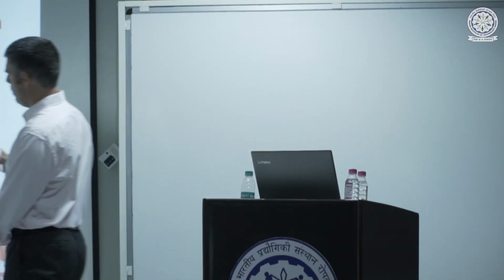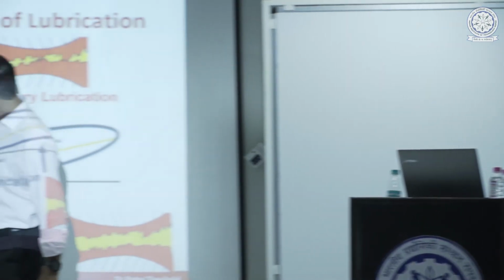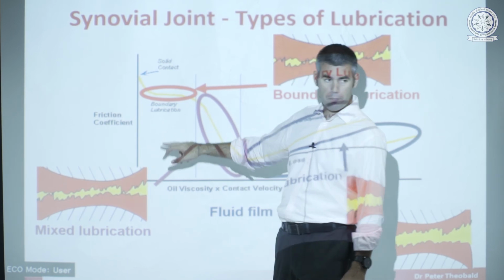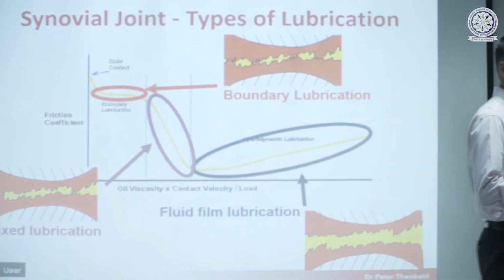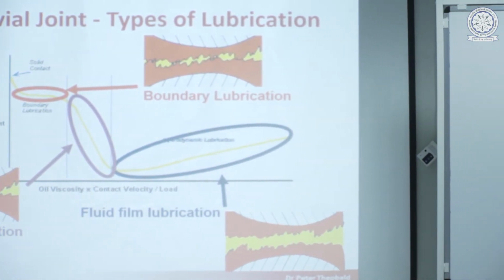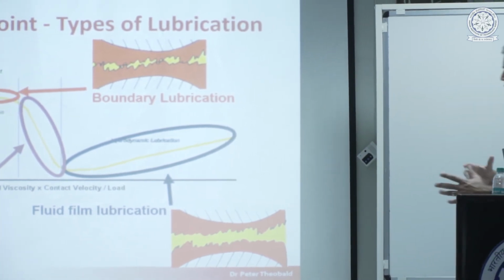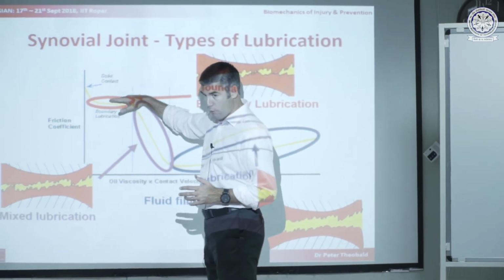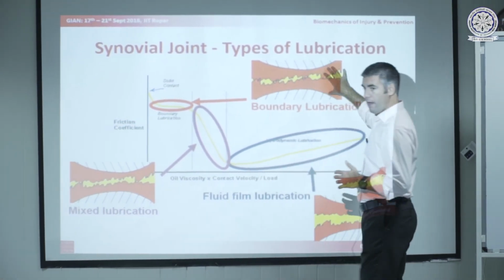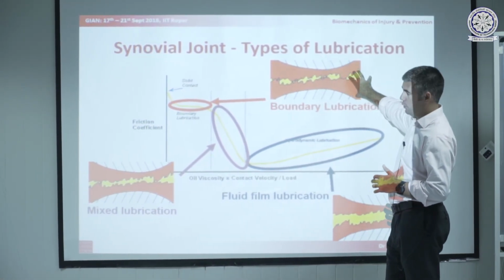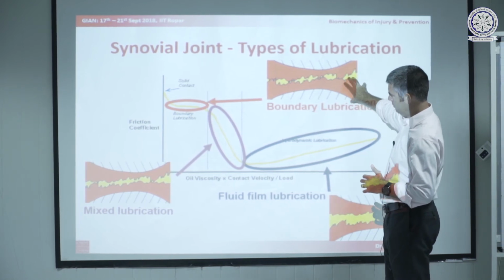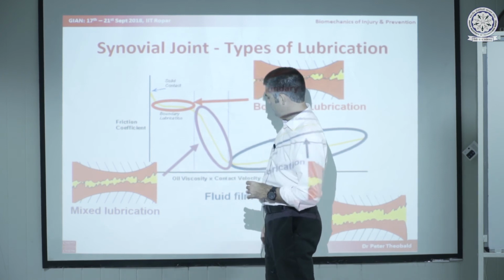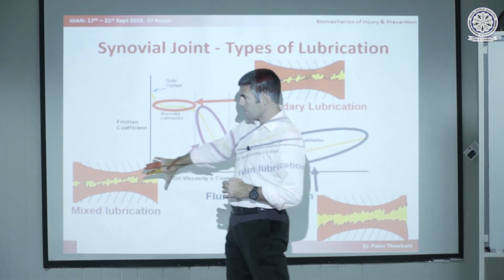So the parameters of the human joint put us about here somewhere, which causes problems. And we'll come to those problems later on in terms of trying to understand how our interaction can be described. We can't really describe it as boundary lubrication because that scenario wouldn't give us the longevity of the joint that we know exists. And indeed, it doesn't really fall on the boundary condition plot. Mixed lubrication, same problem again.